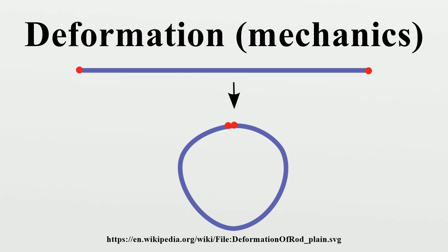Affine deformation. A deformation is called an affine deformation if it can be described by an affine transformation. Such a transformation is composed of a linear transformation and a rigid body translation. Affine deformations are also called homogeneous deformations. Therefore, an affine deformation has the form x = F X + c, where x is the position of a point in the deformed configuration, X is the position in a reference configuration, t is a time-like parameter, F is the linear transformation, and c is the translation.